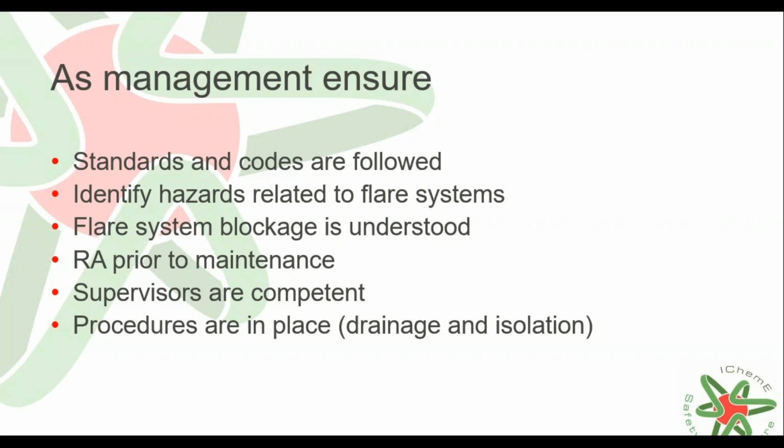It is a major hazard to flare systems, by the way, so I wanted to highlight that. Ensure that rigorous risk assessments have been undertaken prior to jobs of such a high magnitude and potential hazard, such as maintenance of a flare system. Make sure that maintenance supervisors have the competency to undertake responsibilities and to perform their activities to a recognized standard on a sustained basis. This is what we saw in the second case, where unfortunately the supervisor made a decision that he allowed the work to continue.